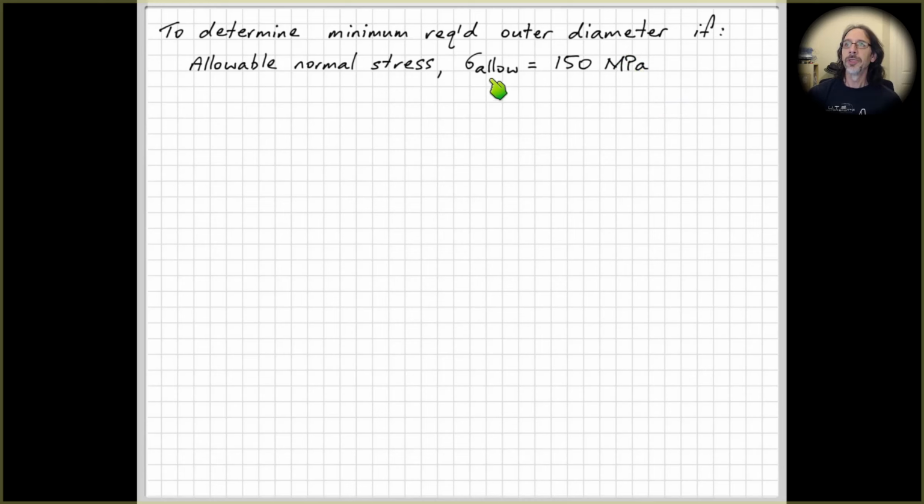Okay, so assuming that the allowable stress that we're given here takes into account the fatigue. Also, we haven't taken into account any stress concentration effects. All right, so this is a very simplified approach, and if you're going to design this shaft properly and actually put it into commission in practice, then you need to do more than this simple approach that we're doing here.